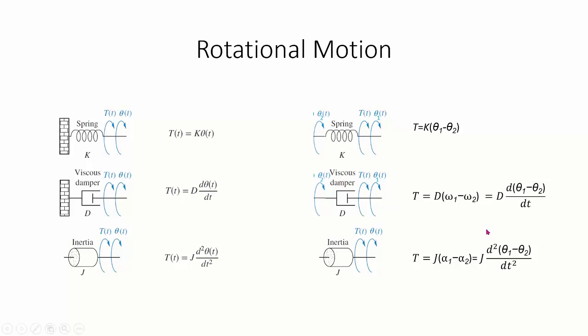So now we are going to use a different abbreviation and syntax for the damping constant in case of rotational motion, while in case of linear motion we were calling this B. And this spring constant should also have been written as k theta, but the book used it as k, so I've also used k. I guess it's better if you call this k theta because it differs from the linear or translational spring constant k. So this is the torsional spring constant k theta.